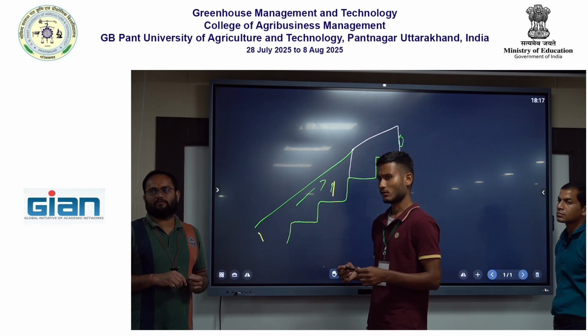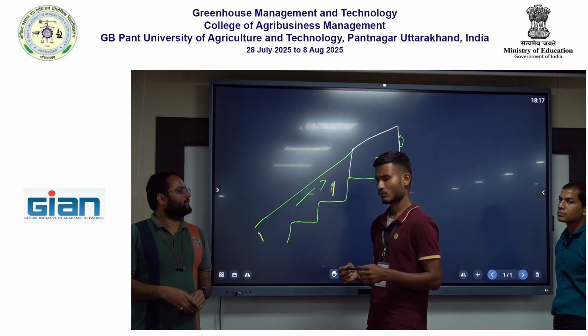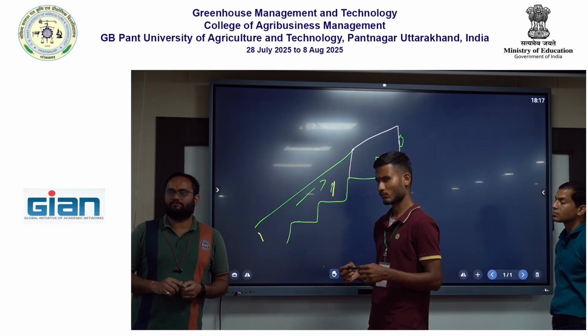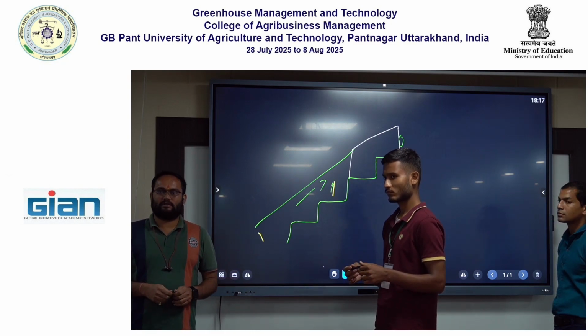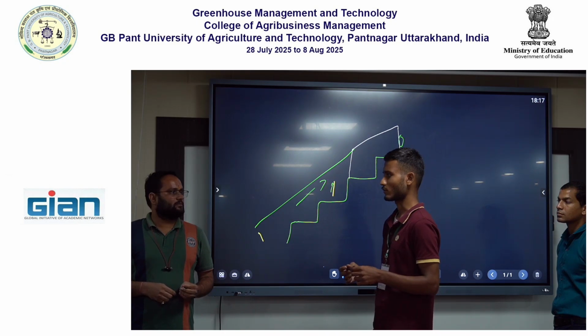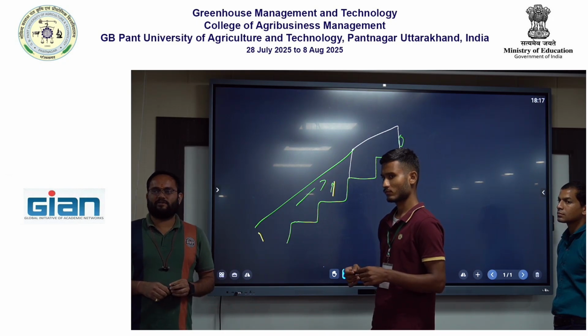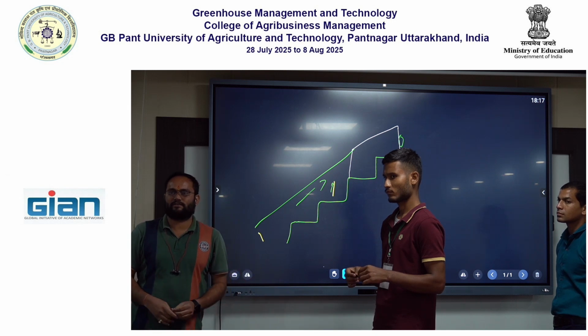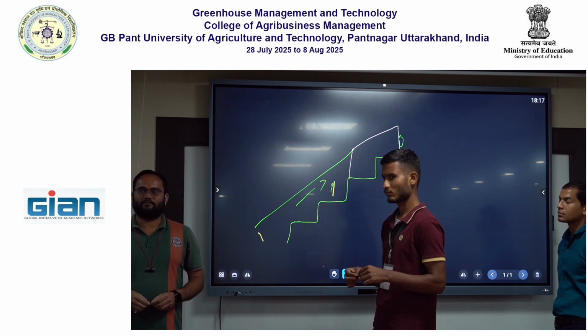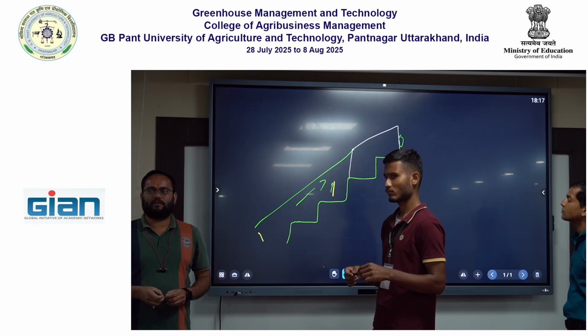Yeah. What I would do is invest a little bit more, and instead of that many terraces, I would make half the number of terraces. Cut the soil there and add it to the other side. If the width is 5 feet, you can cut half the soil and fill it onto this side, right? You still have terraces, but half the number.